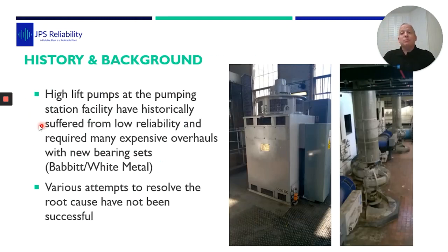So the background on this one was, it's a pumping station, and as usual, we only got involved when they had repeat failures and they kept trying to fix it, and when they couldn't fix it anymore, they thought they'd give us a call. So we came along and we looked at these large motors, 5,000 kilograms, about 3 meters high and about 1 meter and a bit square. Sleeve bearings. At the top is a tilting pad thrust bearing and a radial tilting pad bearing, and it's a tilting pad radial bearing at the bottom, and it's got a 6 meter cardan shaft down to a pump.